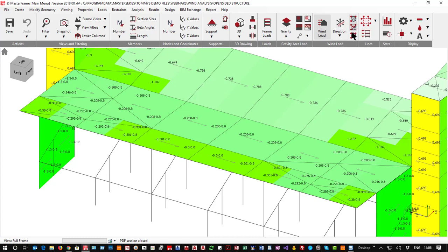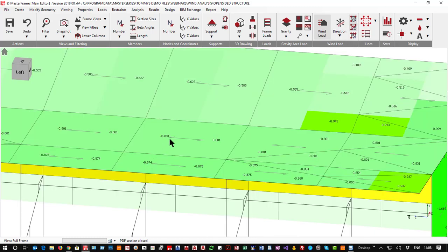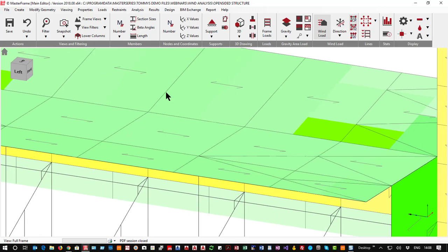If I take the values, 0.87, 0.88 and 0.627, when we go to P1, that increases due to the internal pressure. This doesn't change because this is a canopy. This is an internal surface with internal pressure, so it has distinguished between the two very, very simply.